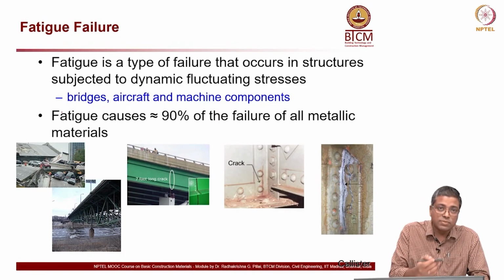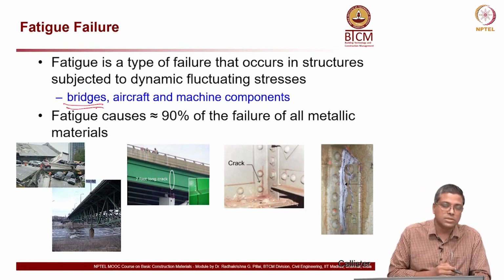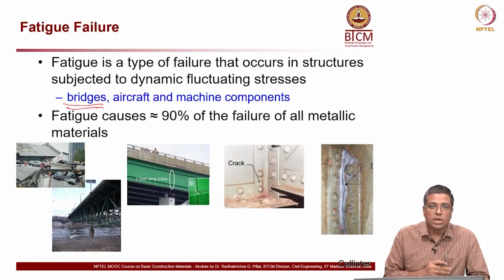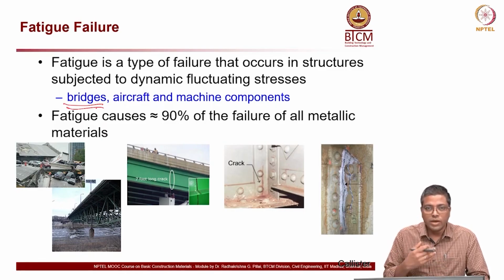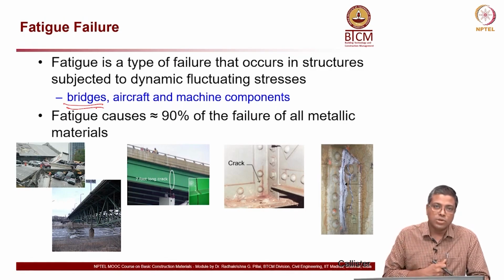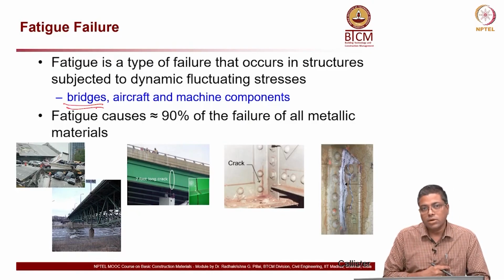So, in case of civil engineering, we have bridges. Definitely there are steel bridges, steel structures, but the steel bridges are more prone to fatigue failure because bridges are used for vehicles. So, you have moving loads on the bridges, like vehicles when they pass, it's like vibrations are induced onto the bridge structure, and that can lead to this kind of fluctuating stresses which lead to eventual failure.